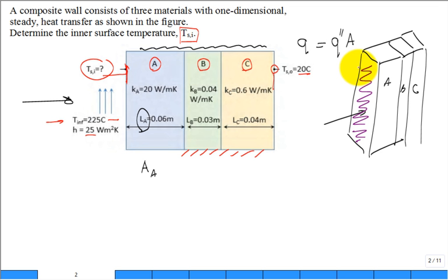Well, we're probably going to employ some sort of flow through a network. So think about having a resistor, node connected by resistors, and even out here we have a resistor for a convection. So 3 conduction resistors and one convection resistor. These nodes have temperatures.